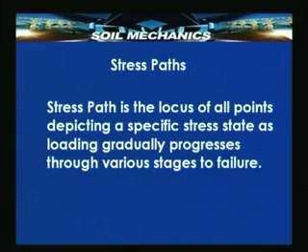What is a stress path? Let us take a look at the basic definition. It is the locus of all points, that is, a line joining certain points which depict a specific stress state as loading gradually progresses through various stages and finally causes failure.